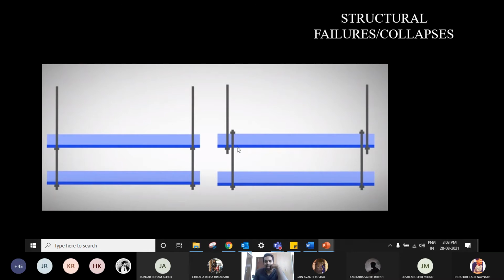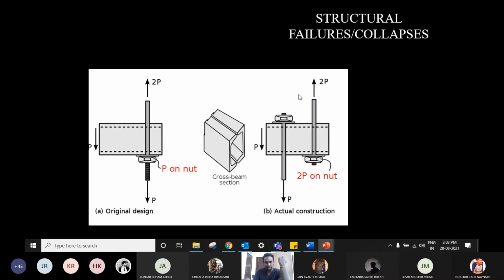So one thought, like, okay, this is a small arrangement that we can get away with. It's easier to construct, but somebody has to back check. I told the shop drawing needs to be checked by the structural engineer again and approved, but they did not do it. Nobody actually looked at this in detail. They thought, okay, it's going to be the same, and they approved it. And what happened was the collapse because of that.